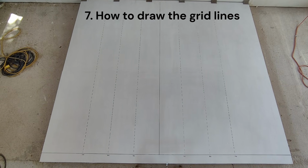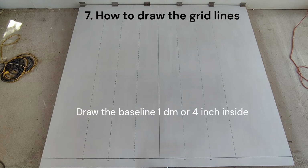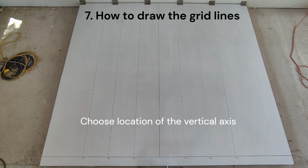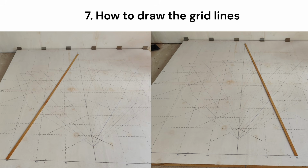First, you need to choose where to draw the horizontal baseline. Draw it 1 decimeter inside the lofting table. After this, determine where you want the vertical axis to be located. Now you must take 2 distances to the left and right of the intended vertical line and swing arcs with a piece of wood. One end has a screw or a nail, the other end has a pin. Swing these arcs as you can see in the picture.